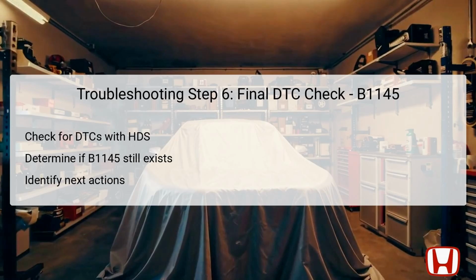Conversely, if the light indicating DTC B1145 is off, it indicates that the system has successfully recovered from the problem, suggesting that the previous troubleshooting steps addressed the fault. This check is vital in concluding a successful troubleshooting process.